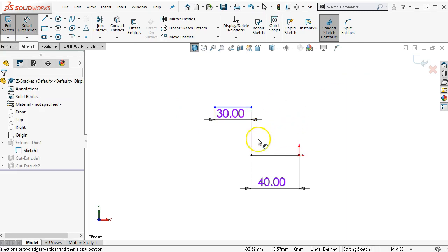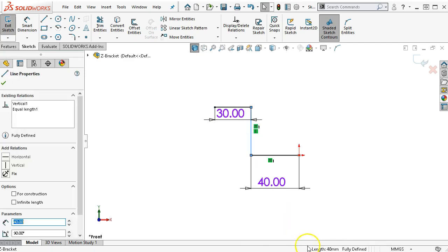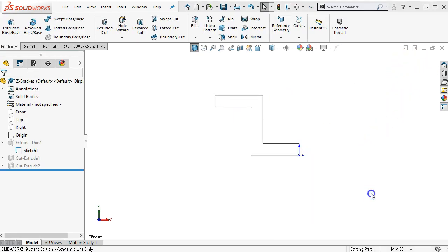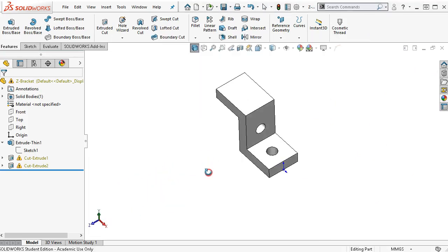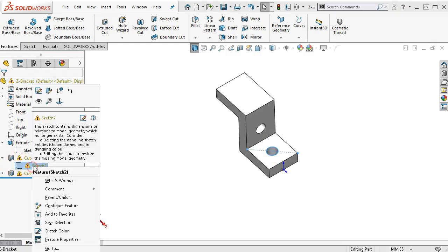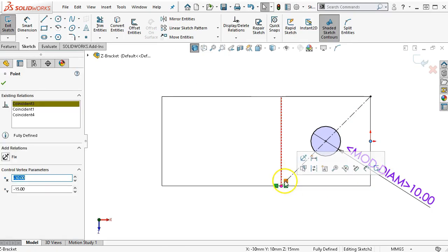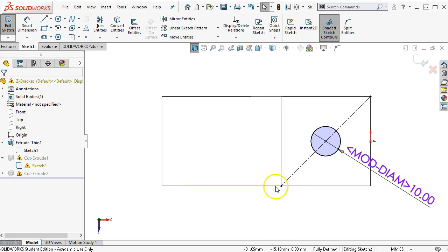Alright, so actually 40 and 10, well, didn't need to do that. I didn't do my math, and once we add the 10 millimeters, it'll be right there. So if I do a Control-Z, just to do a quick verification, length is 40, goes out the other 10. We'll go ahead and see what it did. So warning, and this is something that we kind of expect when we start manipulating these, that if the geometry changes, if it does something, it loses track of those elements, then we're going to see something, a piece of geometry go to underdefined or can't be resolved.